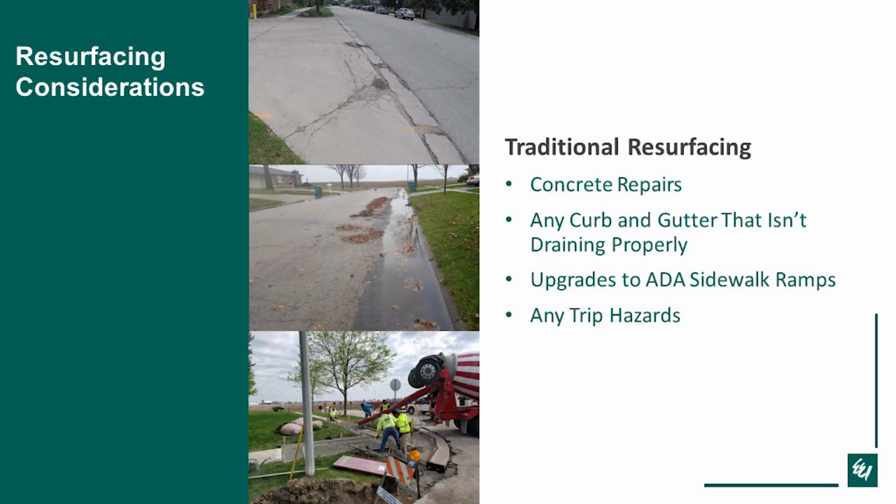So concrete repairs, each community is different and has their own standards, but at a minimum, typically you want to fix anything that's not draining, such as the picture there in the middle. That picture at the top, you'd probably want to fix that curb as well, because you're going to get a lot of moisture going through all those existing cracks, going down into your base. And then everyone knows that you got to upgrade the ADA sidewalk ramps to the most up-to-date detail. Whether you want to add any trip hazards or any other sidewalk would be community dependent, but typically it's more cost effective to do it while you have a contractor there than do it in a separate program, but that would be community specific.